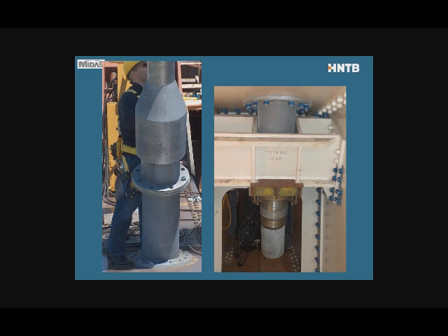Now the cable runs through the upper flange. You can see that here. This is the top of the tower in Blennerhassett Island. You can see the guide pipe running through the flange. Then the flange connection, the bolted connection, is where a damper was sitting for vibration control. We only used that on Blennerhassett Island because it was longer cables than the other bridges. And then sitting on top of that is an anti-vandalism tube. So that's a tube that just protects the cable in the lower portion, but we don't want to have HDPE pipe exposed to the traffic.